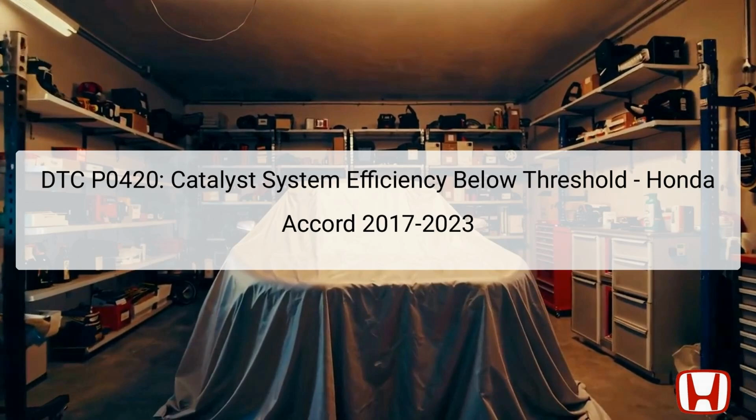The Diagnostic Trouble Code, DTC P0420, indicates a problem with the catalyst system's efficiency, specifically below a predefined threshold. This code is associated with the Powertrain Control Module, PCM, and signifies that a fault has been detected in the catalytic converter's operation. The catalytic converter is an essential component of the vehicle's exhaust system, responsible for converting harmful exhaust gases into less toxic emissions.